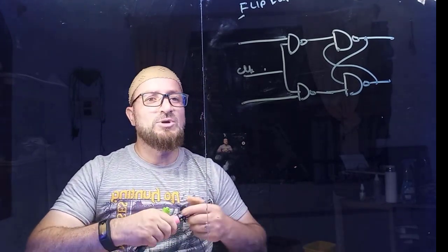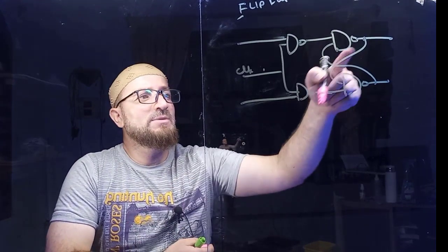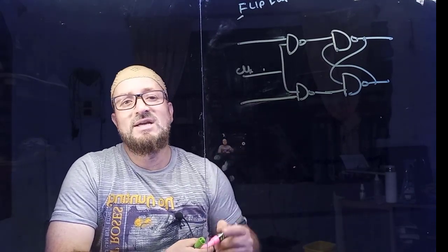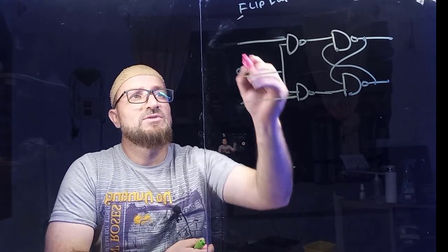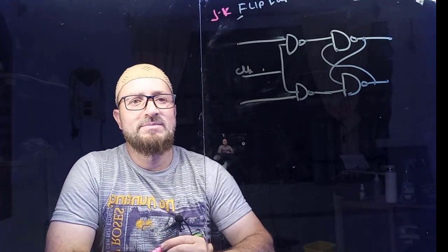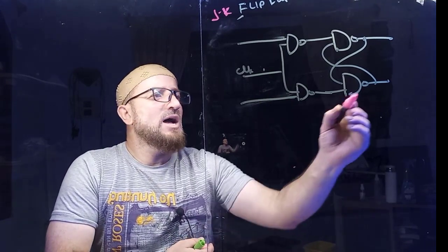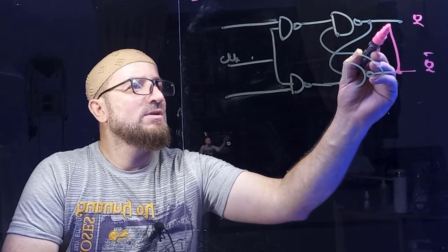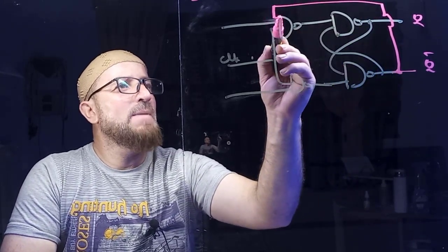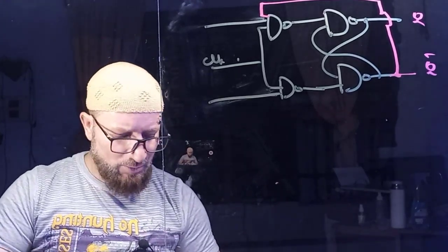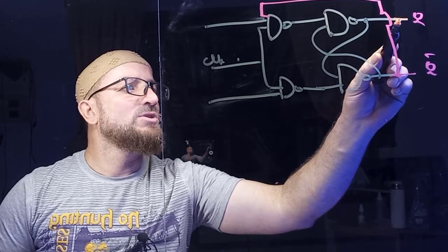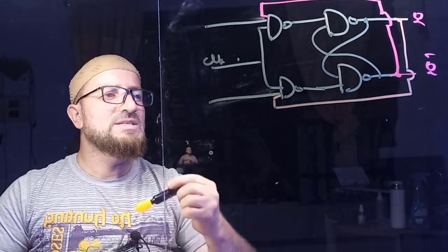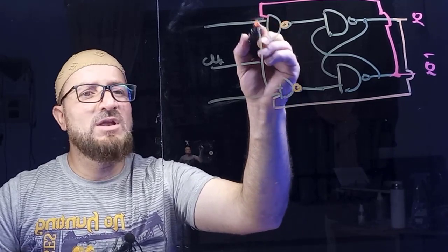So what I'm going to do is put up an additional feedback loop here. That's why it's a sequential circuit. We put the additional feedback loop so that the 1-1 state is put to use. Then it will become the JK flip-flop. So what shall I do? This is my Q and this is my Q complement. I put up the additional feedback loop from here, and come back to this NAND gate. And I put up another feedback loop from this Q to this NAND gate. Okay, now these NAND gates have 3 inputs.